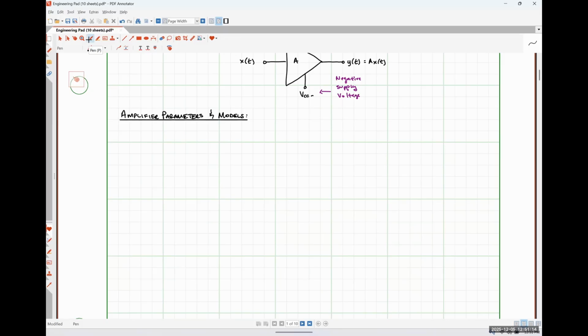Probably the most simple amplifier is a single transistor amplifier, which will have a single transistor and then anywhere between 3 to up to maybe 5 or 6 different resistors that are used in various biasing configurations, okay? And then your more complex amplifiers, like the internal circuitry inside of an op amp, can be tens or hundreds of transistors, tens or hundreds of resistors, capacitors, inductors, diodes, and all of that kind of good stuff.